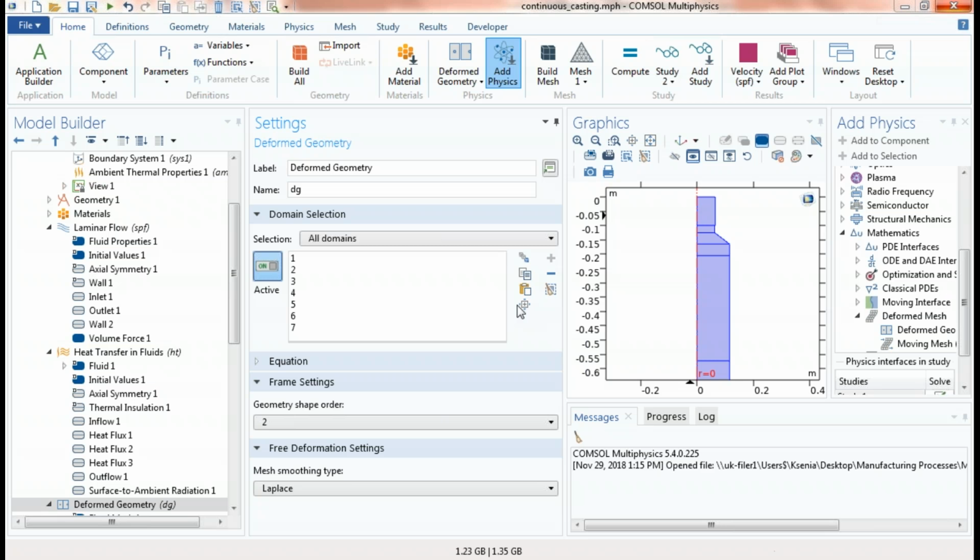Now, rather than actually modeling the rotation of the upper part with respect to the lower part, I think it would probably be easier to apply a load to compress the two together and use maybe some analytical expression based on the rotational speed to generate a heat source, and then apply that heat source at the interface between the two different materials.